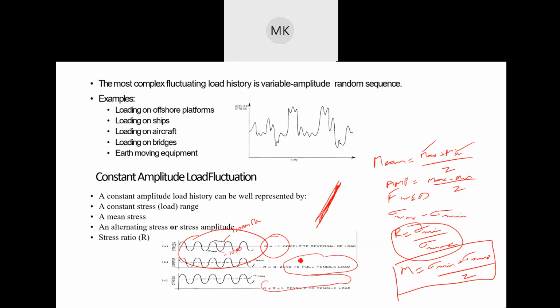Most of the testing that you do in terms of test results and any kind of application that we do are generally some version of tensile loading. R of 0.1 is the worst kind of tensile loading, because the stress range is 90% for those materials. So it's the worst condition, but you can do a 0.5 load ratio and stuff like that.